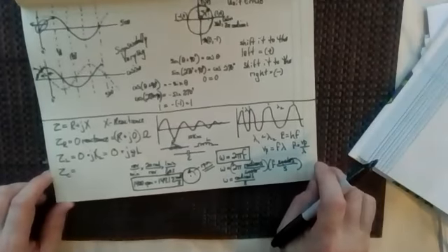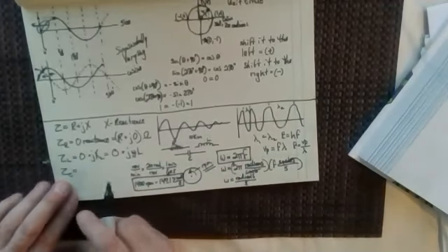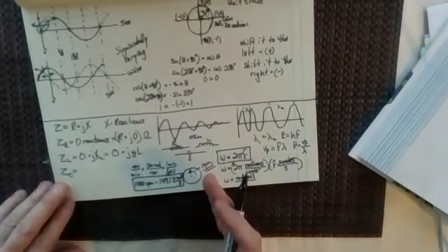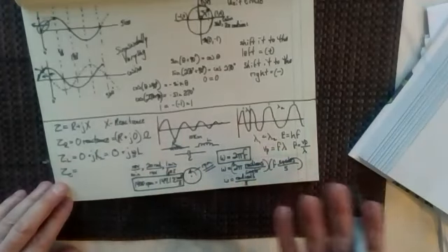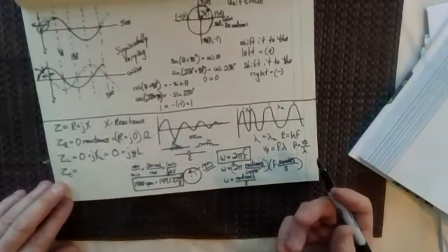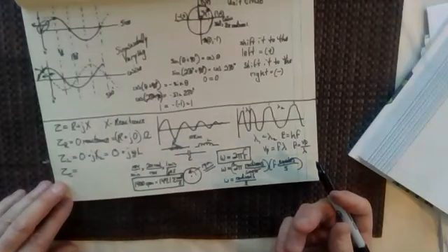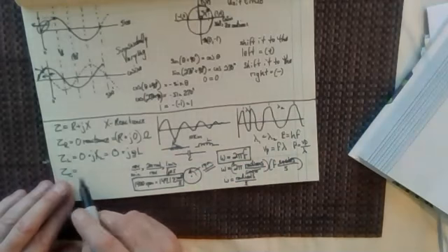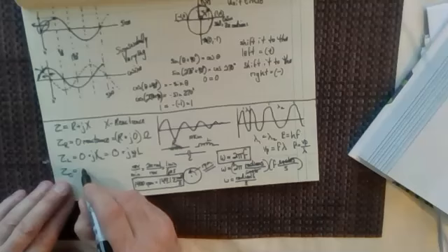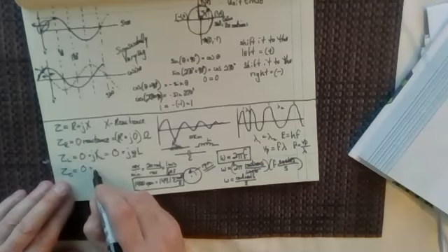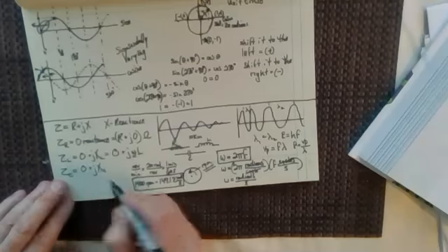I've just realized I should probably switch this book around. I've got capacitance, and a pure capacitor is actually much closer to reality than the inductor, because the inductor has huge windings of thin wires, so that's obviously going to cause some resistance, isn't it? Whereas the capacitor is really just two plates separated by a dielectric, and that makes this much closer to reality. And so this is 0 plus j x sub c.